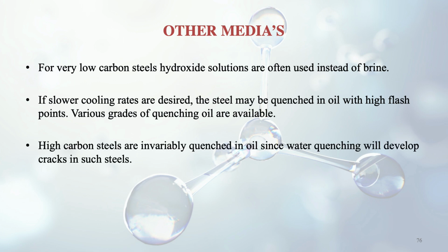High carbon steels are invariably quenched in oil, since water quenching will develop cracks in such steels. So with high carbon steels, we never use water; instead we use oil, because it helps us get rid of the cracks which would come due to water quenching.